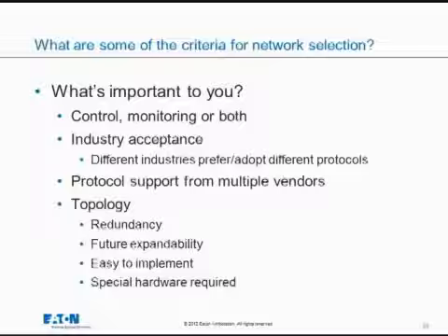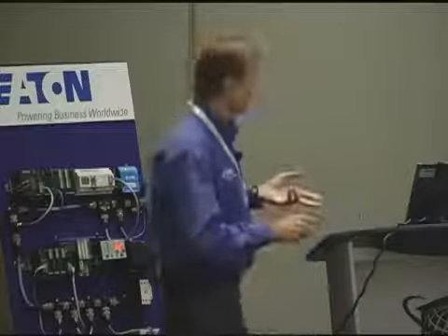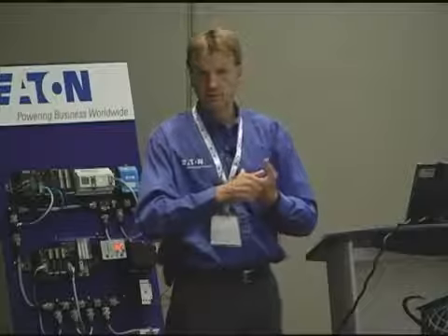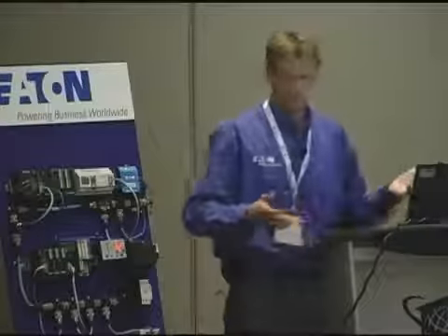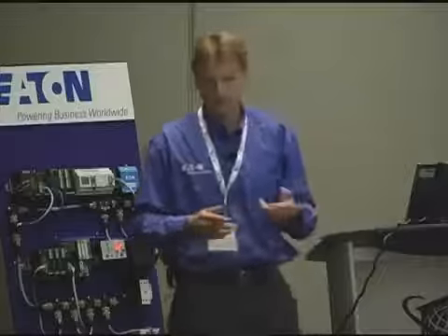Is the protocol that you selected supported by multiple vendors? Are you fixed to just having that one vendor's product, or can you use anybody's product? It allows for more flexibility. We talked about the topology. Do you need redundancy? Do you have to expand in the future? And if we have to expand, can we add nodes on the fly, or do we have to shut everything down to do it? Is it easy to implement? That means a lot too.